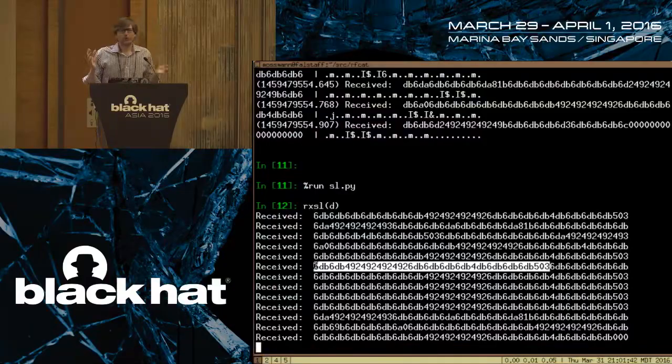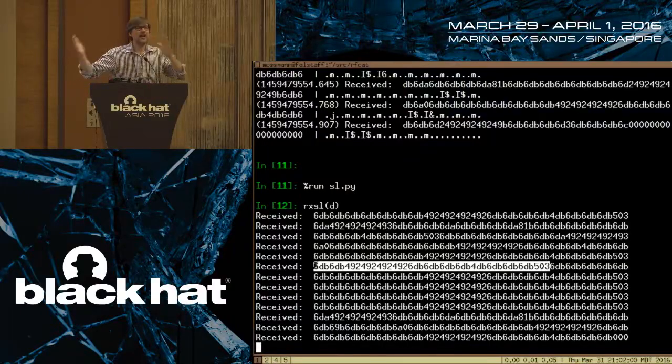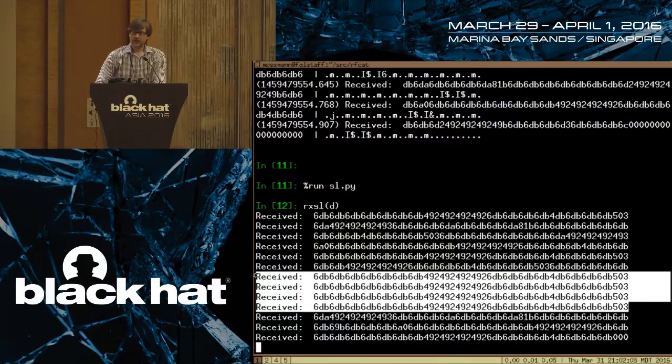Basically, I have a problem where that preamble matching, like I'm configuring a sync word to be the beginning of the preamble, but it doesn't take very many bit errors to get a false positive match of that sync word. And since that preamble is so repetitive, sometimes I get a false positive match where I'm just out of synchronization. So most of these are good, like this block right here. Those all line up perfectly together, which is a good indication that they're lined up correctly. But some of these other lines are off by a little bit.